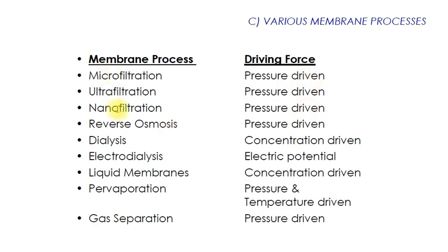These four work on pore-size separation, or pore flow separation, and the driving force in these processes is pressure. In dialysis, the driving force is concentration. In electrodialysis, the driving force is electrical potential.